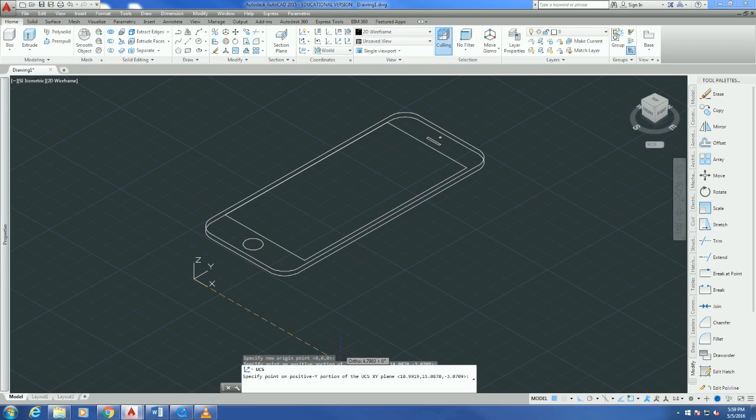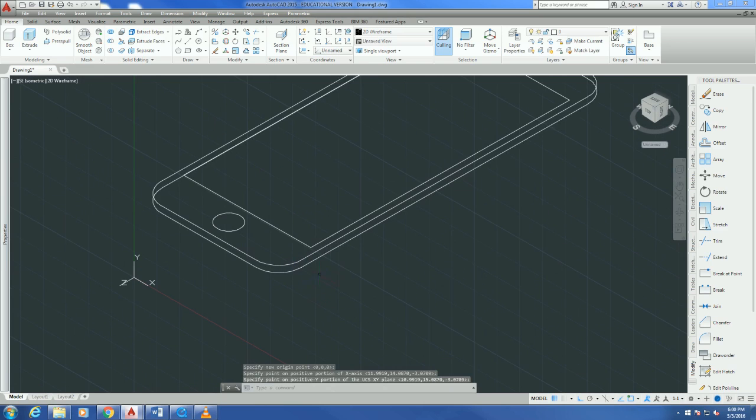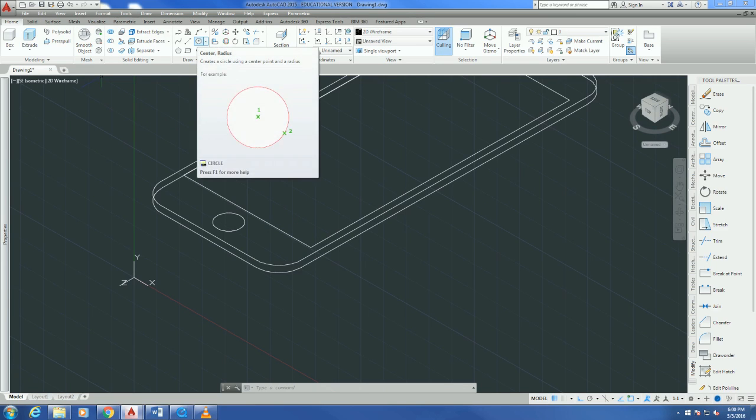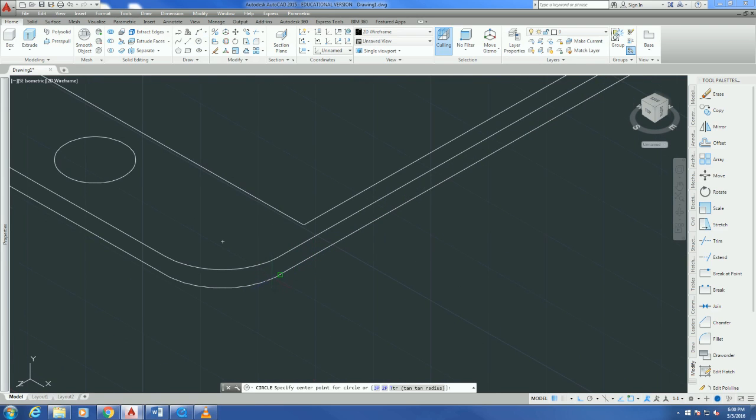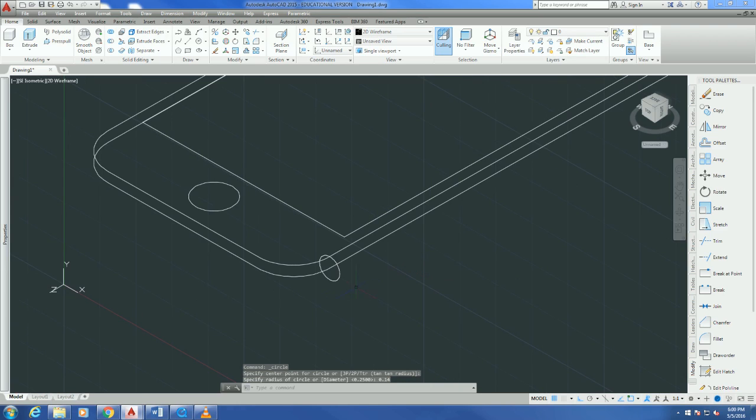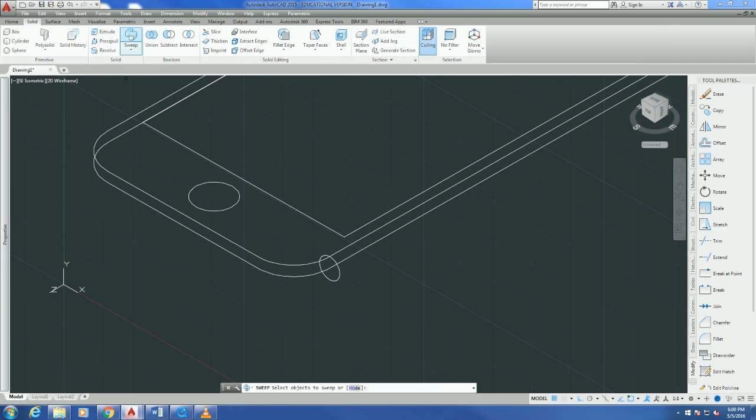This is the X axis, and I'm going to define the previous Z axis as the Y axis, so that I can draw in the new XY axis. Then I'll draw the circle with the radius of our desired pipeline. Once we have the circle at the center line, we can define the pipeline using the command sweep.